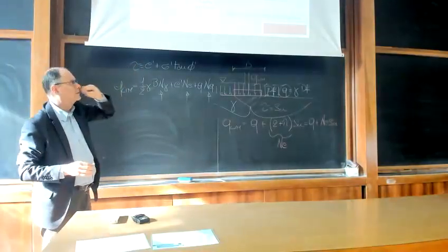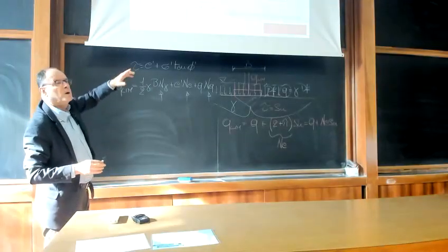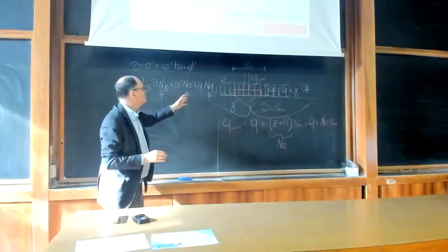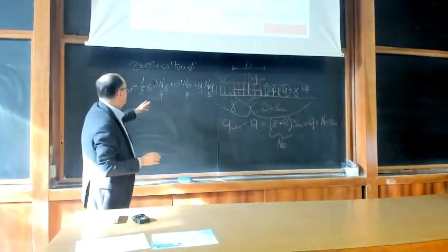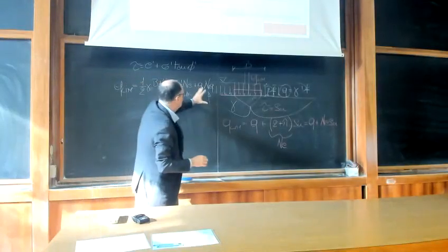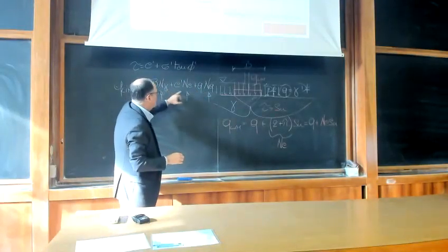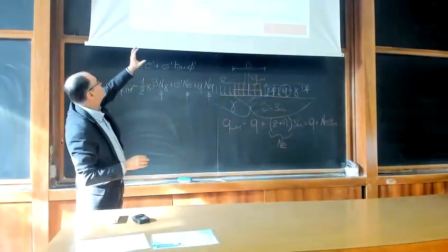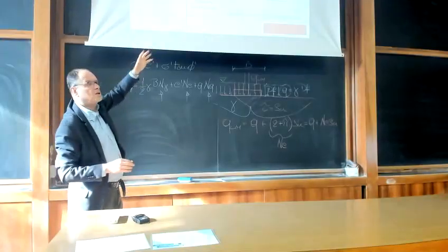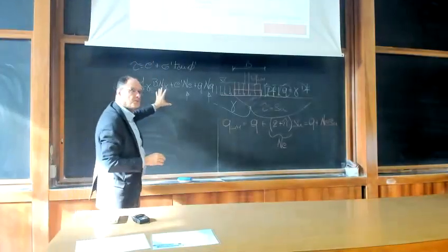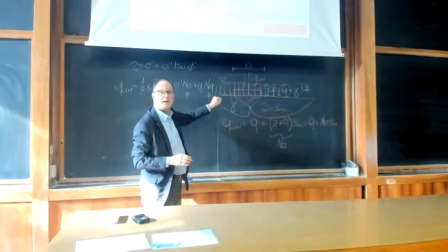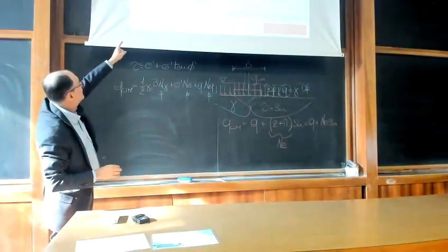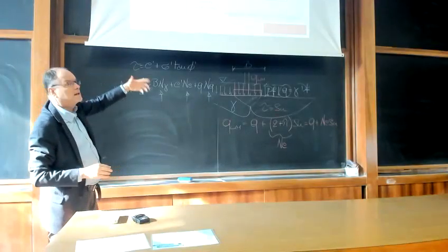Drained, undrained, considering the soil weight. So this is not exact, but approximate enough. And you see, you have these three contributions, where N gamma, N C, N q are called bearing capacity factors. If you assume a different expression and different analysis, you will end up with different expressions of N gamma, N C, and N q. But they are all functions of what? As you see there, they are functions essentially of Ka and Kp.